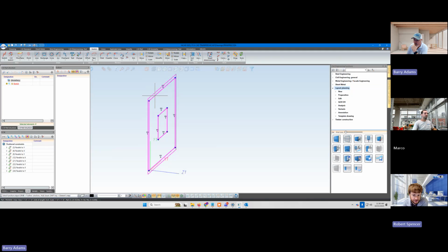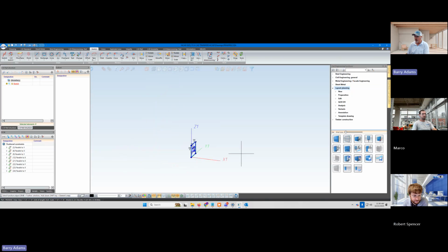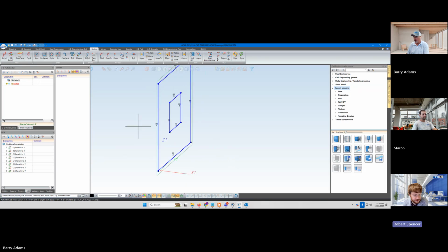Okay. Try hitting W on the keyboard. Does anything happen? Or maybe we don't have that macro installed. Okay. We don't. Instead of that, go to the drawing ribbon at the top. And then go all the way over to the World CS button. And just click the button, not the arrow. Click it again. I did.